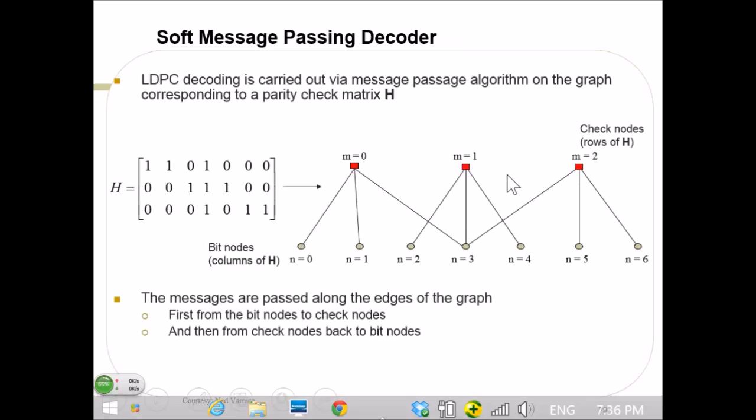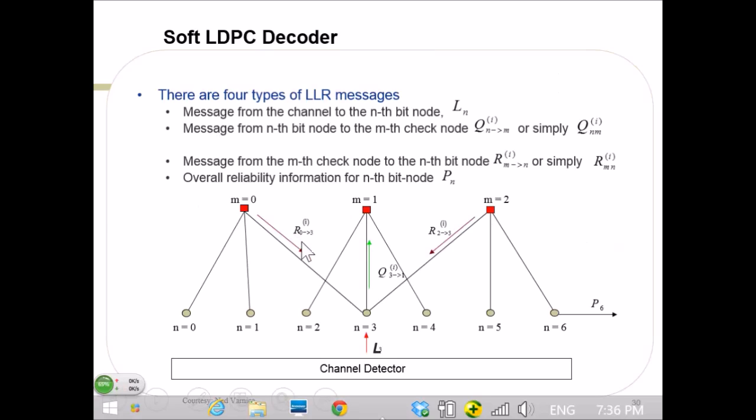And then in terms of the soft decoding, previously we simply used unsatisfied checks to determine which bit to flip. What we're doing now instead is that we have all different kinds of messages. One is what we received originally, the message we get from the channel. And then for each bit, the easy way to understand this is that the bit is telling each check whether it is reliable or not. So it has its own opinion about itself, and it communicates that to the different check nodes.